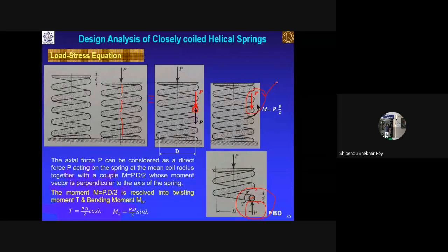So this is the external thing. This P is the external load passing through the CG of the cross section, and after approximation, it's not M. Now T will be P into D by 2, that is external, and the resisting one will be this one. Now you individually treat these two things. This is my T, where T equals P into D by 2. This is the resisting couple, and because of that it will create torsion, so over the cross section, torsional shear stress will be induced.